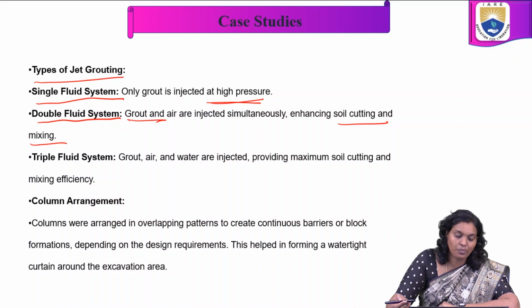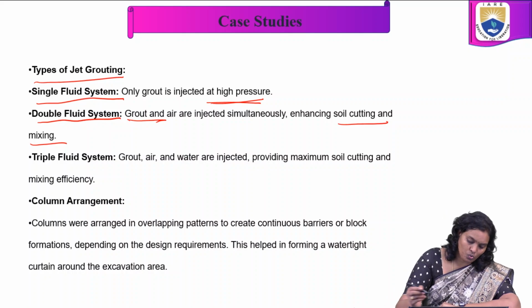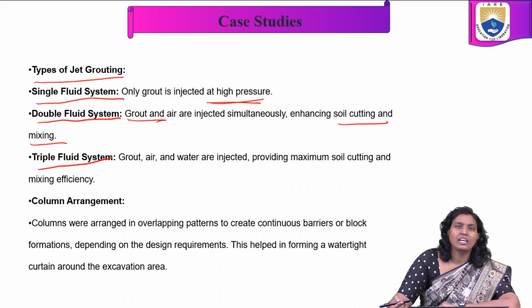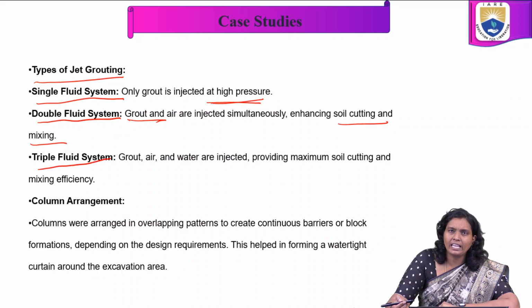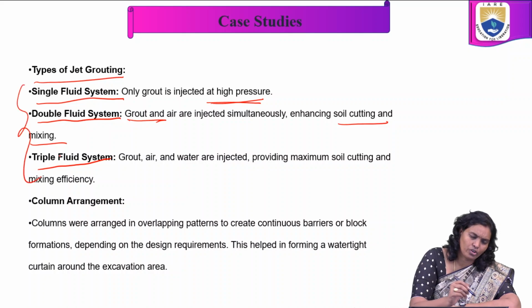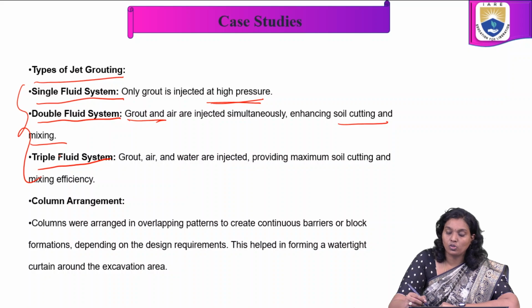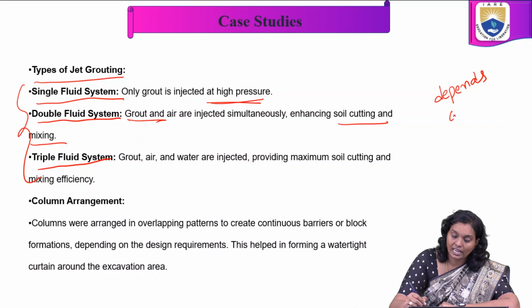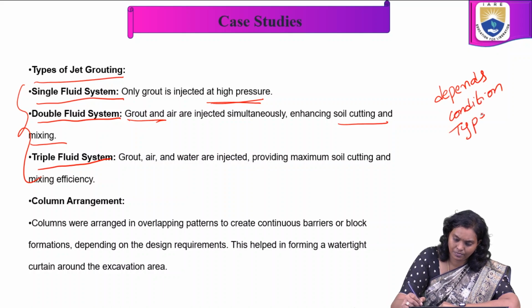The next one is the triple fluid system. Whenever we require the maximum soil cutting and mixing efficiency, we choose this triple fluid system. It is nothing but grout, air and water injected, providing maximum soil cutting and mixing efficiency. So depending upon the conditions, we choose the type of grouting.